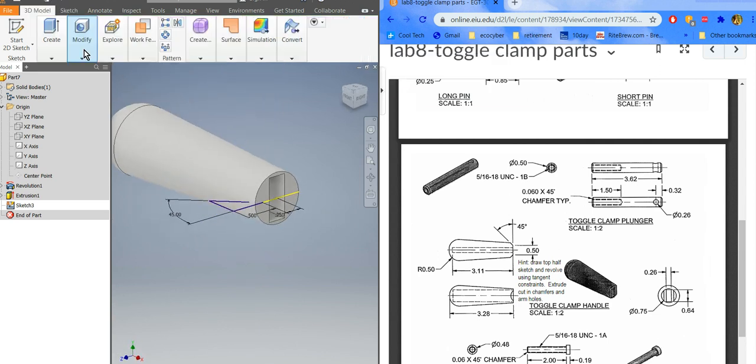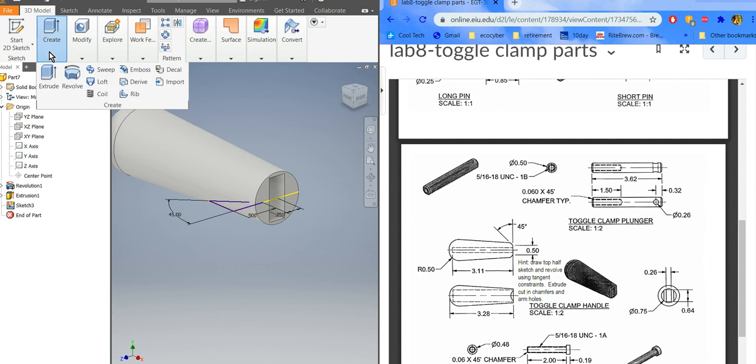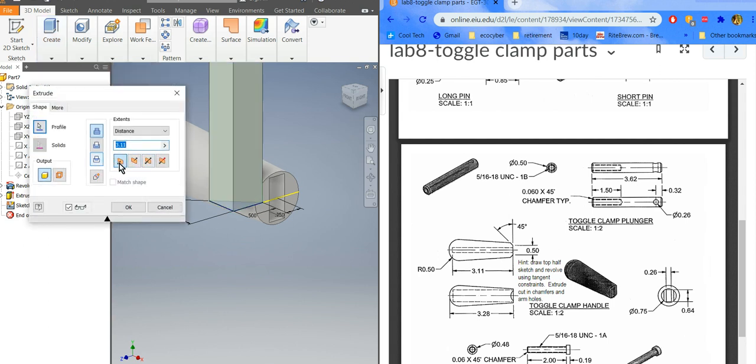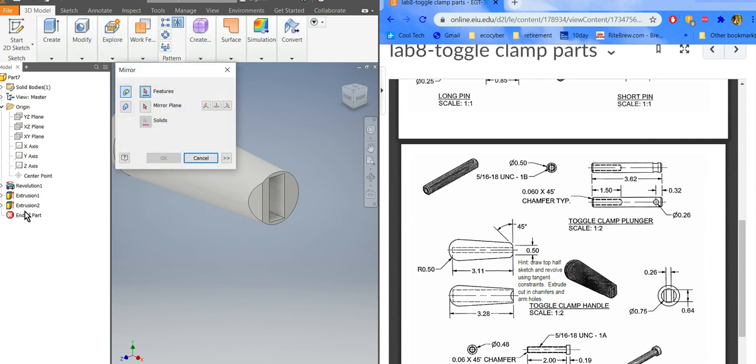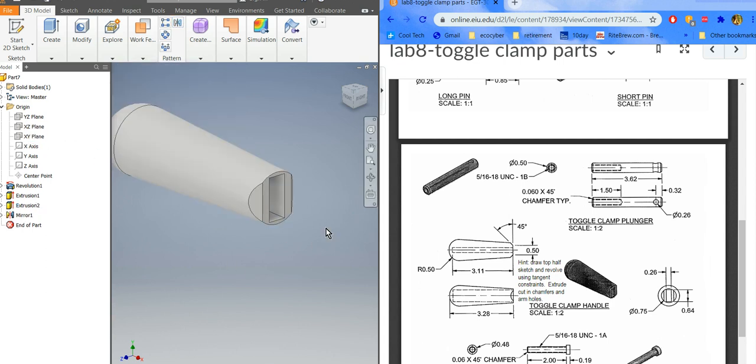Finish sketch. Then we just cut that thing again. Extrude both directions. Okay. All cut. Kind of lost itself there, so now it's showing up. Hit OK. So you got it. Alright, now we need to mirror that to the other side. So there's mirror. Pick the last one. Pick my mirror plane. Hopefully I got one. There's one. The middle, since I drew everything in the middle, and there I've got that part's done.